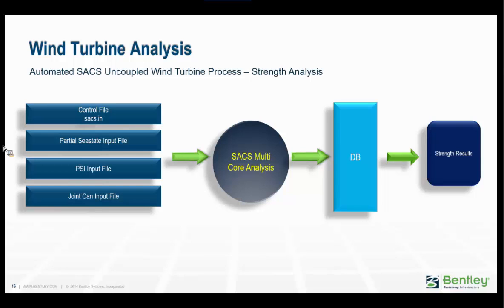In the previous fatigue analysis, I forgot to mention that you can also do a fatigue analysis of the pile foundation itself by generating a pile solution file. So for a strength analysis, we'll input all these files, we'll do a multi-core analysis, and then we'll pass the millions and millions of unity checks into a database. The database is then screened and filtered for the critical unity checks, and we'll supply the information such as the load case in that particular simulation, which simulation, and which portion of the code has been exceeded.